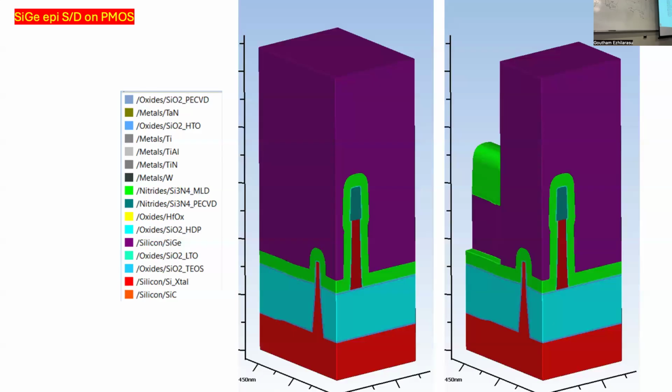So you open up this region, and then you etch the silicon down like this. Right? Or here. And then this is still covered with nitride. And then now when you put this inside the epitaxial growth, the silicon germanium grows here like this. And it is in situ doped, right? In this case, it will be in situ doped P type, so it will be P plus doped. And then you basically cover this again, and then you open this side, and here you again etch down, but here you grow silicon carbide. So when you grow one, the other one should be covered.